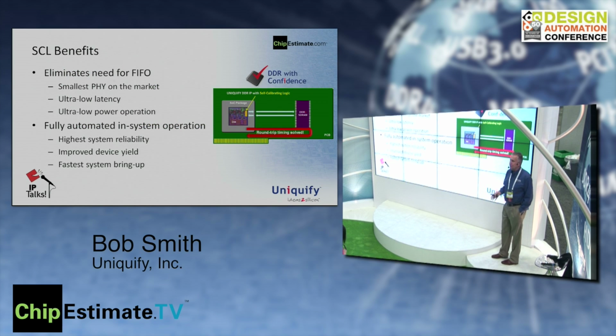There are some other benefits that come with this. It's nice that we added some hardware, but actually because we've added this hardware, we completely eliminate the need for a FIFO for solving this clock domain crossing problem. And that gives us the smallest PHY on the market. We also have the lowest latency PHY. We're about 2.5 to 3 clock cycles less latency than a typical FIFO-based PHY.